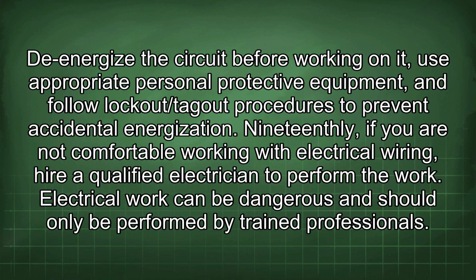De-energize the circuit before working on it, use appropriate personal protective equipment, and follow lockout/tagout procedures to prevent accidental energization.